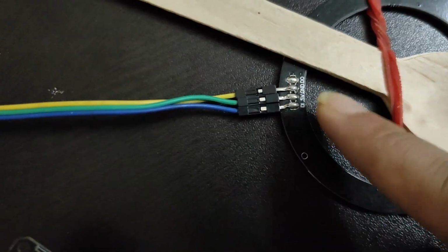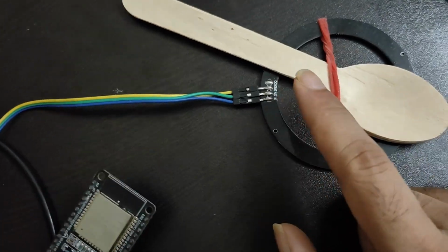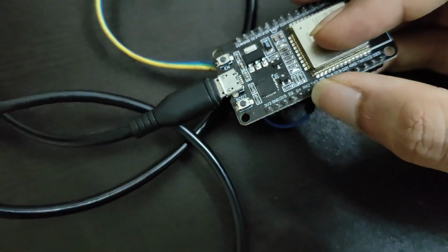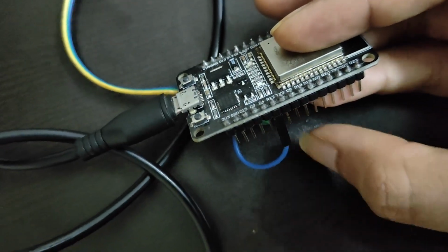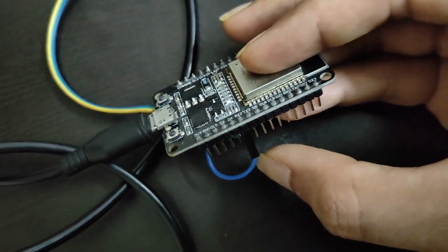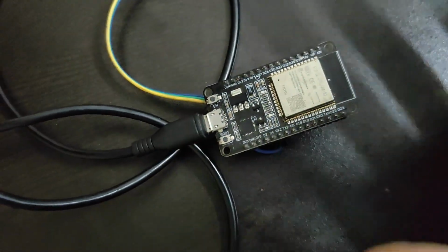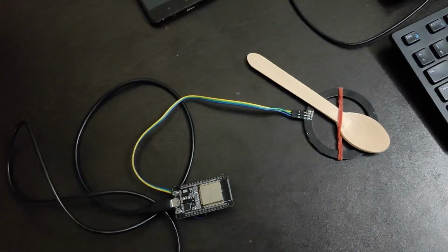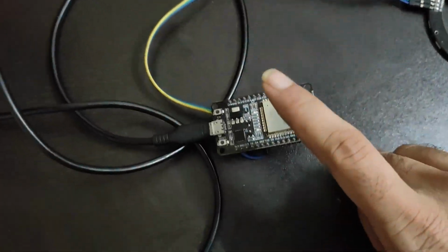And let's talk about this D1. D1 is a signal pin which is used to control the brightness, turn it on and off, and control colors of the light. By default you have to connect it onto pin number RX2 on this ESP32, like you can see, I have connected it here. Or you can also change the pin number of this D1 pin, which you can set in the settings, which I will show you further. So yeah, this is it for the connection part. Now let's talk about the software part, like how you can install the firmware into this ESP32.